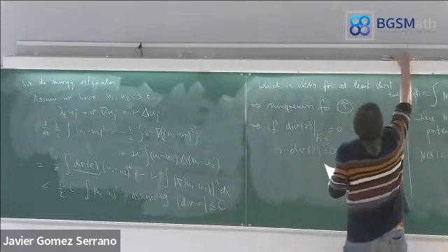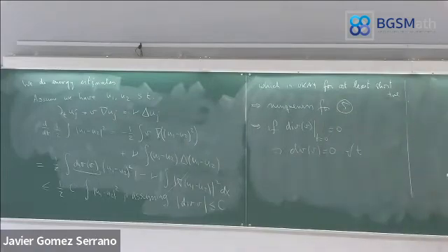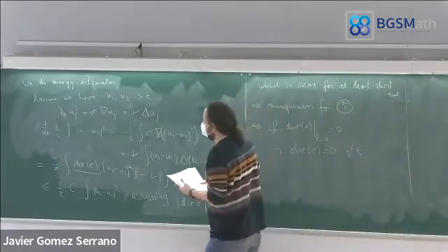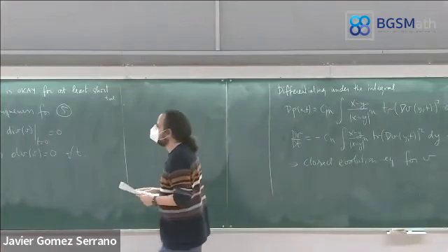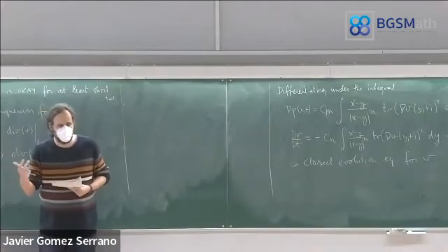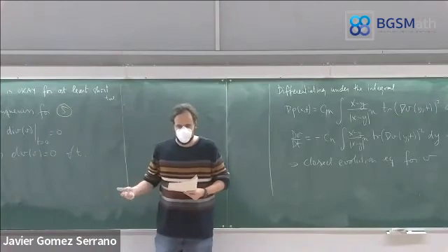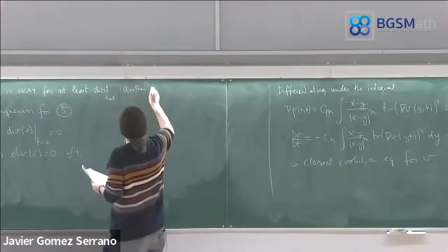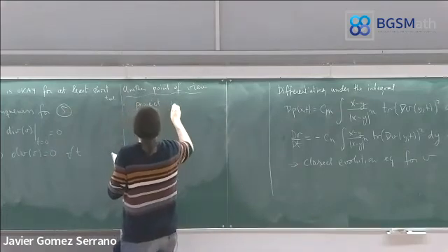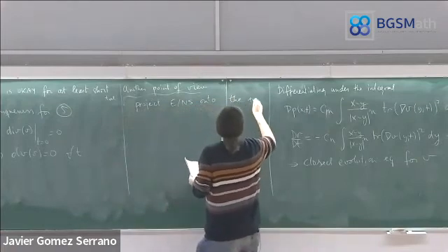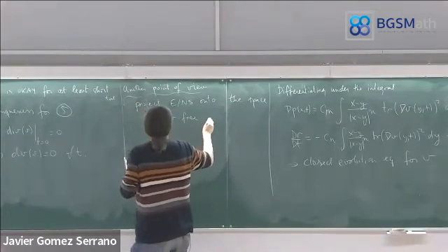Just to maybe give a different point of view of what we have done here. When we got rid of the pressure and tried to get a closed system for V, this looks sort of like magic, but because we can solve for the pressure, life is good. But if we think about what we are actually doing here, we are projecting the equation and everything onto the space of divergence-free vector fields, and then looking at the projection of the equation in that space. So another point of view of what we're doing is to project Euler or Navier-Stokes onto the space of divergence free vector fields.